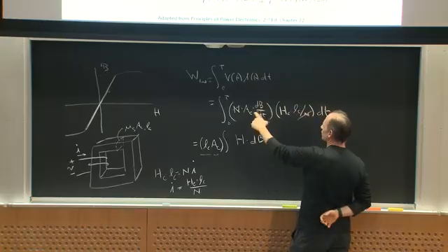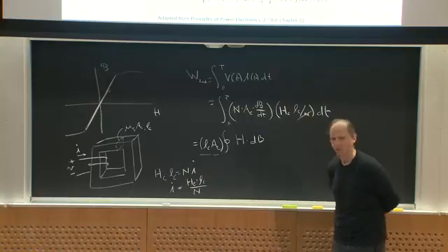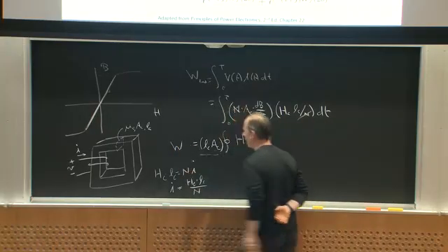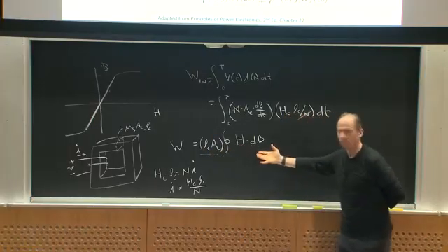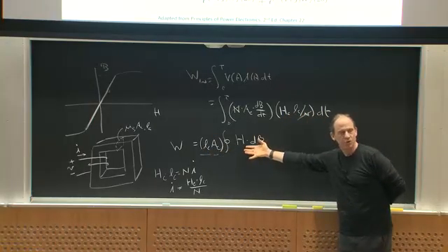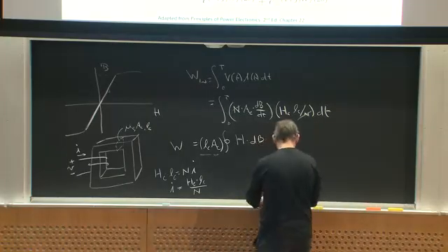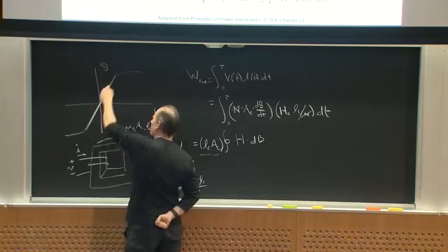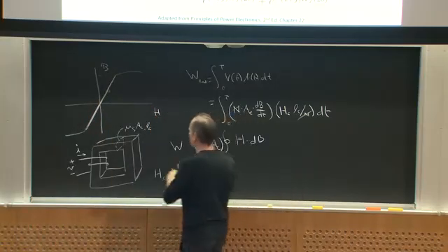And I'm going over a cycle, so presumably B is looping, so this is around a closed cycle, all right? So this is the energy I lose in cycling around. It's the integral of HdB in the core. And what we will see is that in a real core material, B and H don't quite go up and down proportional to one another the way this illustrates. What you really see is something that does this.